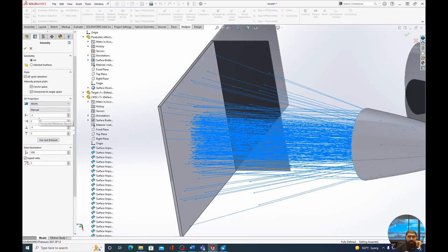You'll notice before it went from -50 to +50. Now it goes from -1 to 1, and this is because in this direction we are looking at a value of cosine from -1 to +1, and data resolution we will keep at 100. So this will split from -1 to 1, but take the sample of how many angles are subdivided in both directions.